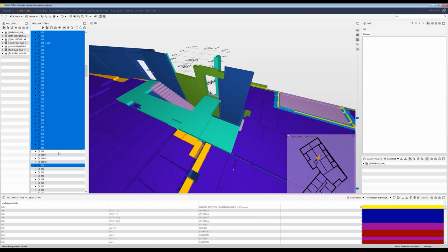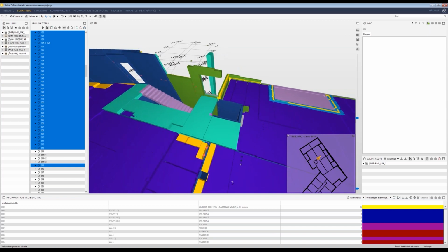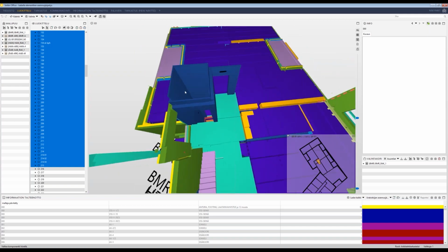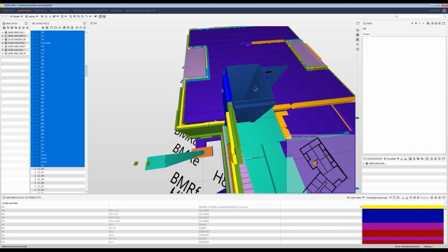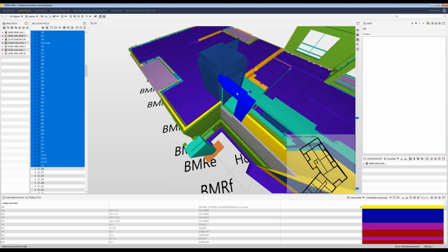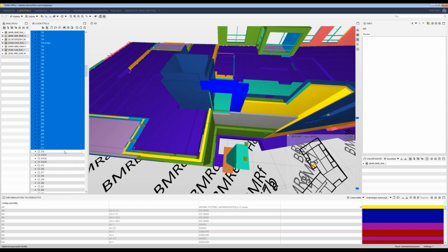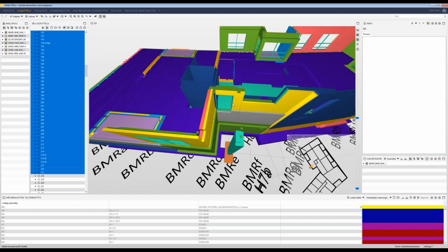So what we did here was to modify the plan so that we added the inside walls just before this one wall part that sits on top of them. The reviewed version would look like this, so that those walls are installed first, and then we continue in a similar fashion.